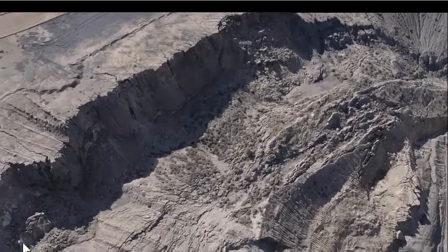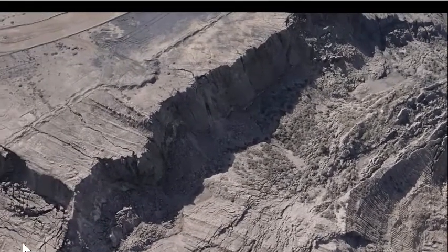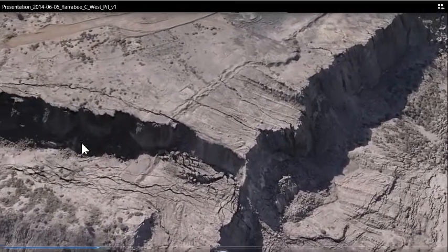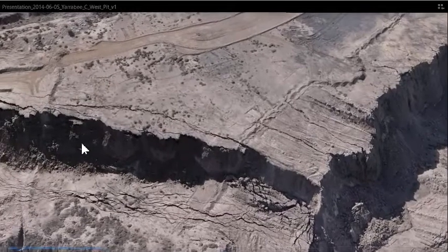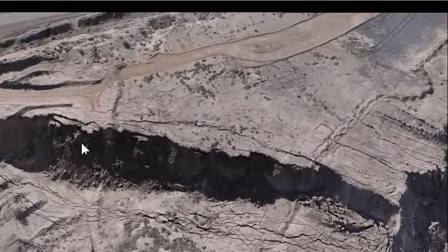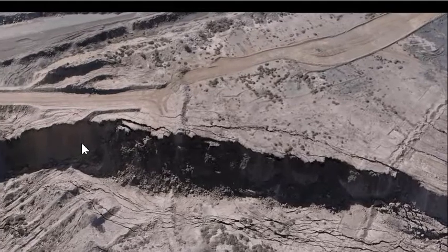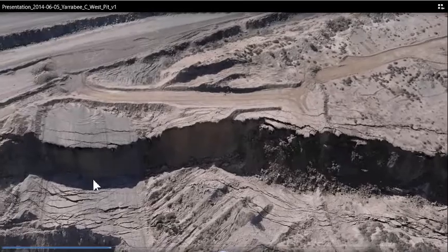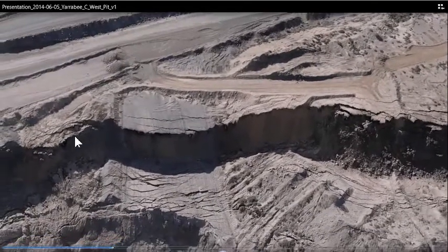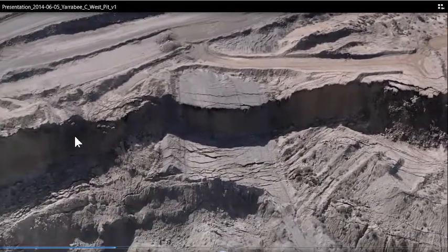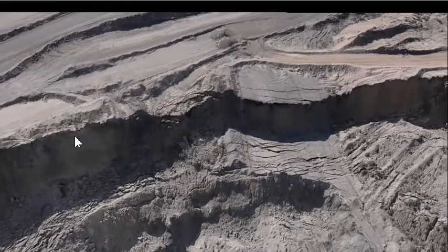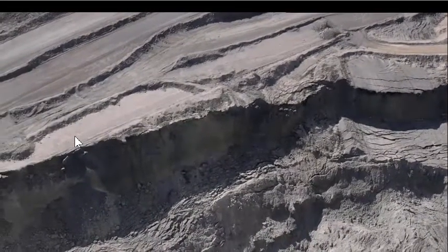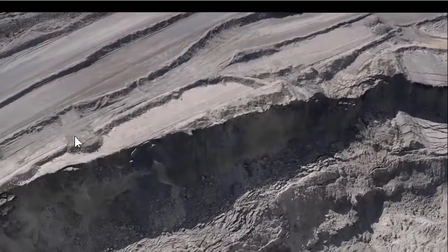As we pan across the model, this visualization highlights a recent area of slumping of up to 10 meters. And with good visualization, we can get a good idea of the extent and the areas affected, as the model is spatially correct. Therefore, we can interrogate it and measure off it as well. This model was created from a 25-minute flight, which took about 1,000 photos and was processed overnight, and the results supplied the next day.